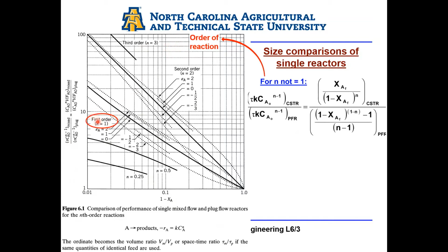For n equals 1, I have a bunch of lines, and the solid line refers to the case where epsilon equals 0. If you recall, epsilon is the fractional change in volume in case we have gases. The dashed lines, when epsilon is 1, 2, minus half, minus 2, 3, also refer to n equals 1, but with epsilon other than 0.